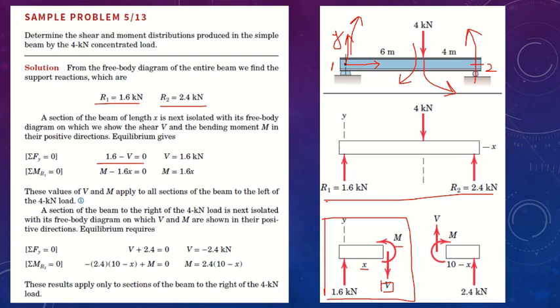Now let's go to the other side. On the other side, after we travel across the beam and reach the other reaction, position 2, we know that V is going to act upward, because we have chosen this direction to be positive. So when we cut the beam into parts, these should be in equal and opposite directions.